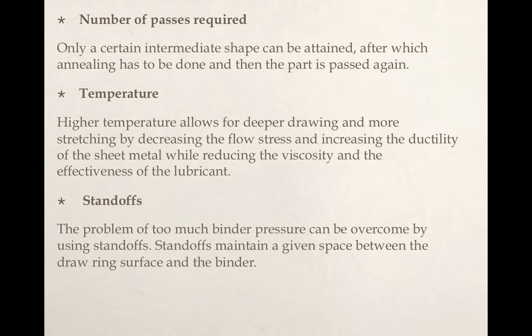And then we have the standoffs. Standoffs basically maintain a given space between the drawing surface and the binder. So too much binder pressure can be overcome using standoffs. If the standoff gap is too small, the material will be pinched tightly between the drawing and the binder surface, reducing its ability to flow freely. And if it is too large, the material will wrinkle during the compression.